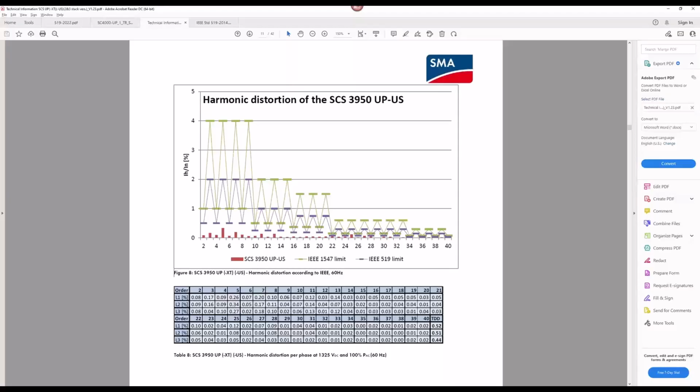The second question is, if there is a capacitor in the system, should we model it or not? The answer is, it depends. It depends on whether your capacitor is far enough from the POI and whether your utility system takes that into account. What we studied here is that we only care about the PCC harmonic demand distortion, and the distortion within our own system. As long as you have established an agreement with that, then the project scope will be determined: what's the current injection at your PCC, but not within your system.